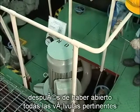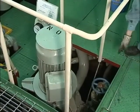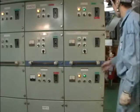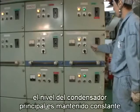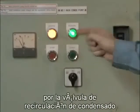After having opened all the pertinent valves, start the main condensate pump. While the main engine is running, the main condenser level is kept constant by the condensate recirculating valve.